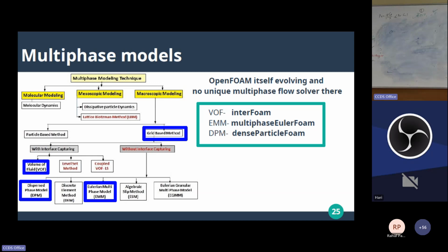Correct. So basically when bubbles are there, if you go with a gaseous Eulerian description on a mesh, it may not capture your interfacial effects. So for that purpose, even though it is gas, they treat it as pointed gaseous bubbles present at random locations. They may grow based on some simplified model, and they try to handle them the Lagrangian way, with Newtonian equations like F equals ma. At first sight it looks like a mesh must be there for gas.